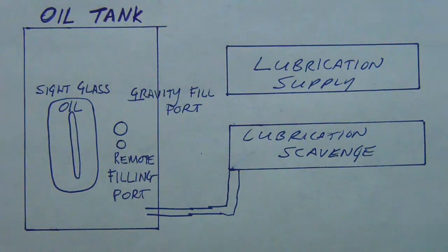So all to those bearings, 1, 2, 3, 4, 5, and your forward and aft sump of the engine. Also, a little bit on keeping the oil clean along the way before it comes back, and also cooling it. We also talked about pressure, making sure that the oil is at a certain pressure. The supply pressure should be at around 35.